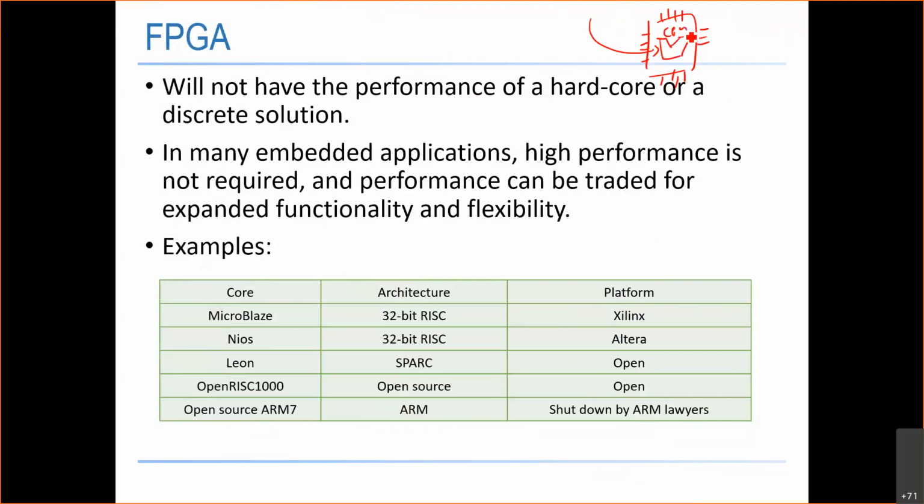If you want to have this CPU on this FPGA board, we call this a soft core. Some manufacturers provide an available soft core for their FPGA chip. For example, they sell you an FPGA chip and you need a processor design in it. So they say, okay, we also have a soft core for the processor. If you ever need a processor in your FPGA, you can just program it with our soft core.